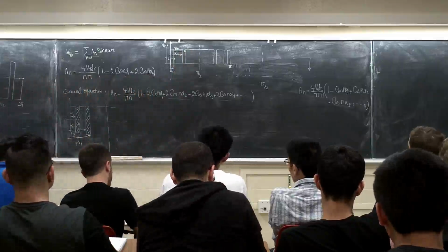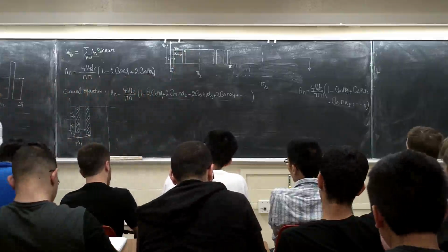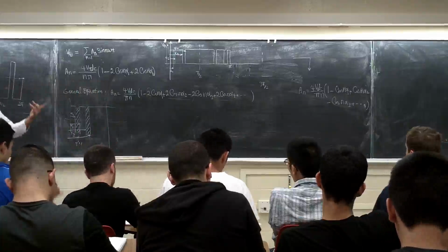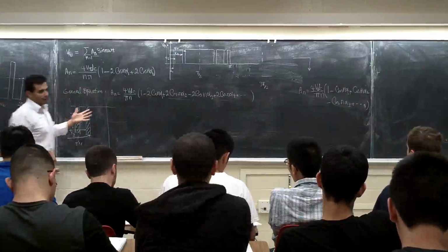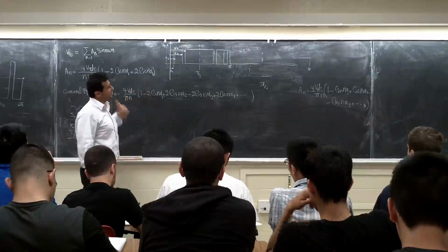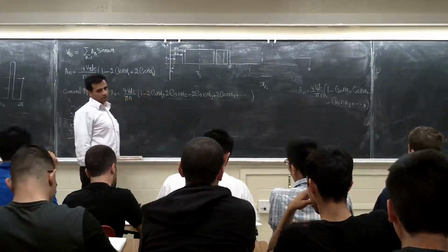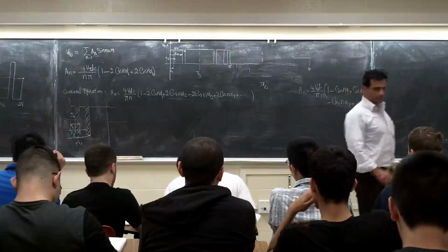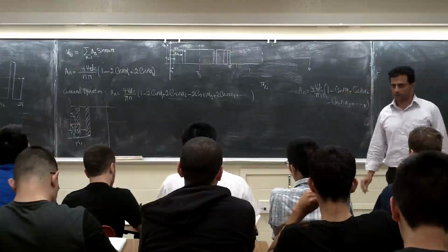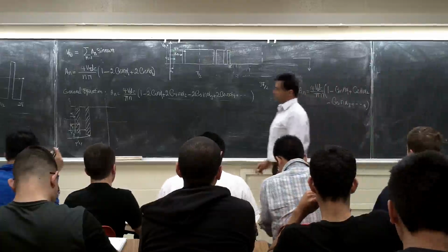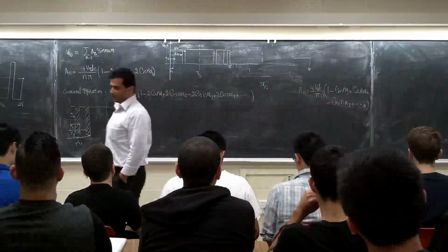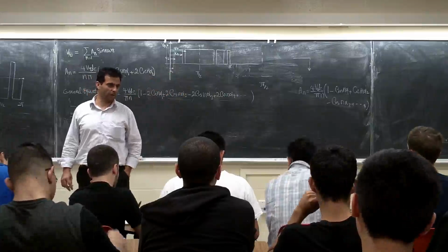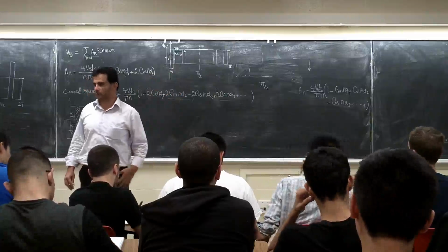We can plot it that way, but the Fourier series is going to be different, because to match this one, we should start like this. This is for bipolar. So basically, for example, they give you, hey, I want to eliminate, for example, I have a 3-phase converter. If I have a 3-phase converter, do I have to be worried about the third harmonics or not? No. Third harmonic already is gone by itself, right? So you are not going to be worried. If I tell you, hey, I want to eliminate the third harmonics and the fifth harmonic, which one do you need? And this much, for example, my fundamental component. For example, this much V1 I want.